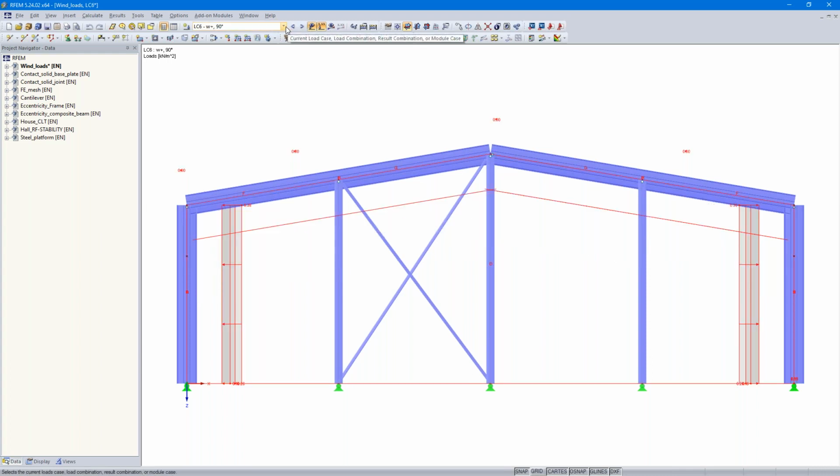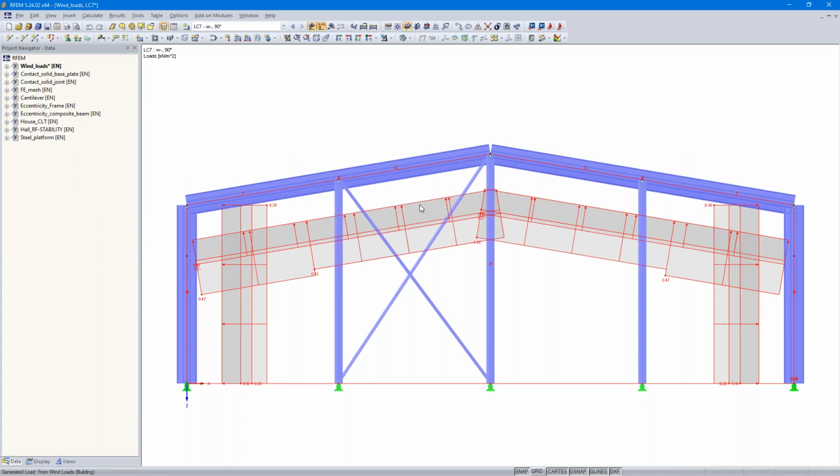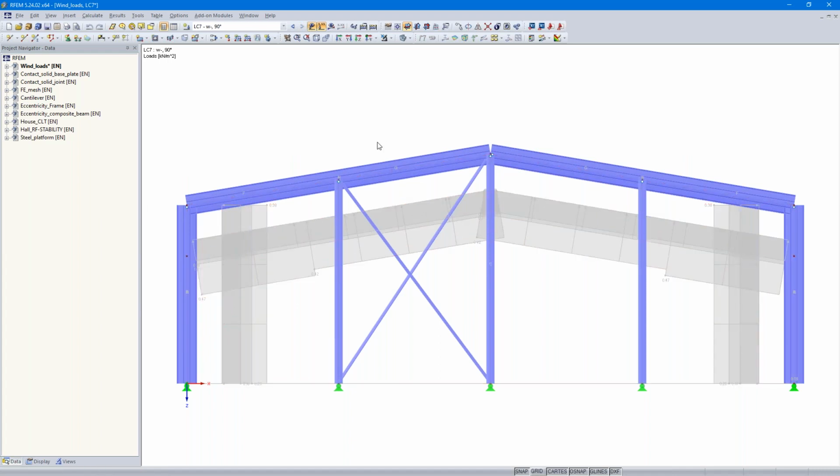Yeah, load case number 6, this load case here, does not contain any pressing wind loads. It can be possible to consider that the suction on the roof acts as supporting, but that depends on you. Important according to Eurocode is this wind load case here.